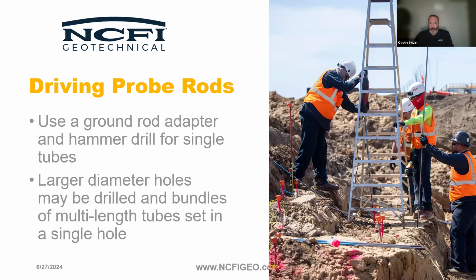If there are multiple levels, you might have extra tubes that you bundle up with others, just in case. What happens if one of the tips comes off and you have a tube that's plugged, or what happens if you have an equipment problem in the middle of injecting down a tube? Well, in that case, you've lost that tube. The tubes and tips are sacrificial.